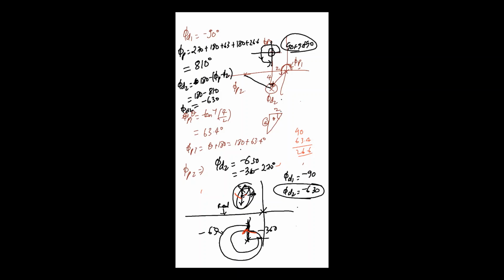I will just erase all the things. Again, draw it. So what we have seen so far is one pole here, one pole here, one pole is at minus 2, like this. This is part of my root locus. This is minus 2 point here. This is going upward, this is going downward. This branch is coming from here, this branch is coming from here.